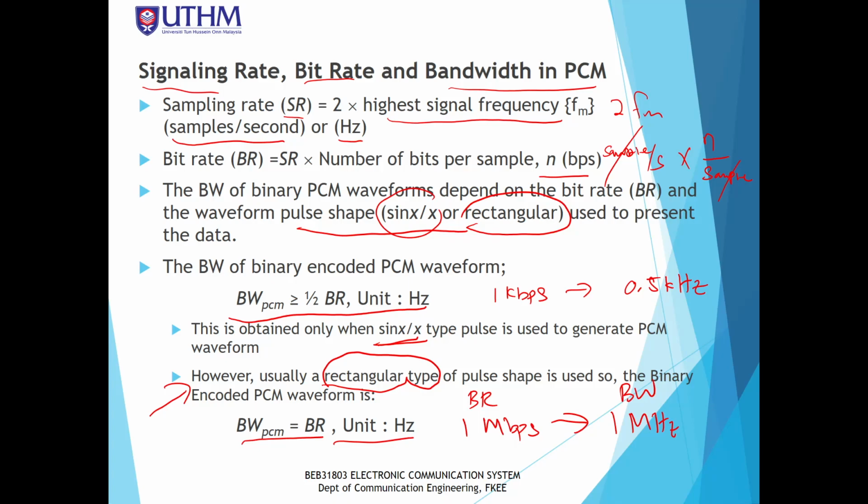In my previous video I explained the basic concept of digital modulation, the basic principle of changing an analog signal into a digital signal. We learned about the sampling process, quantization process, and encoding process, where the signal changes from analog into a PCM code word.